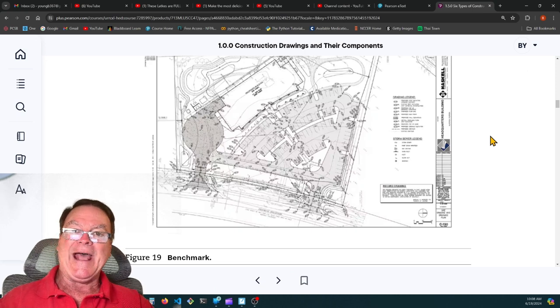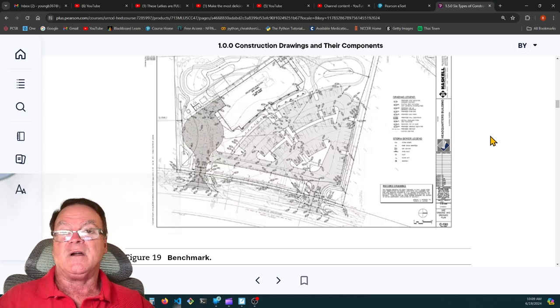You can't just add a lot of earth. If you brought in truckloads of dirt and poured it out and then built a building on it, that dirt's going to settle. That building will lean, just like the Leaning Tower of Pisa. That's what happened over there.